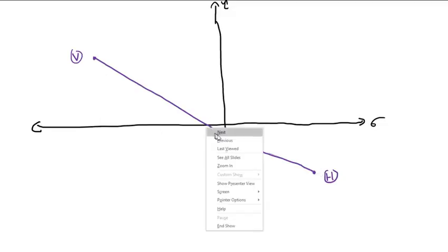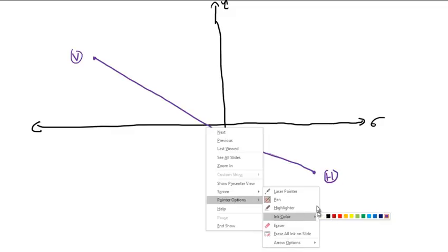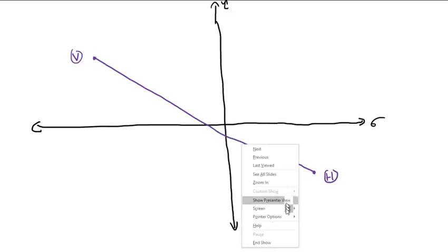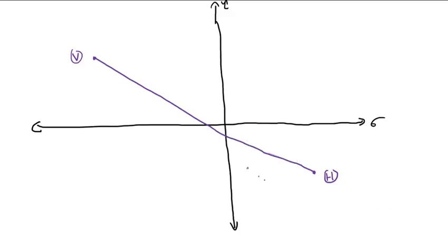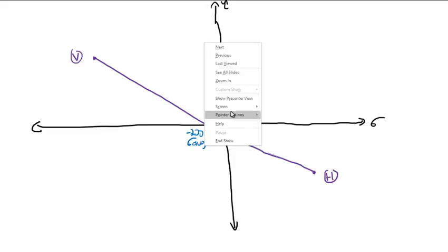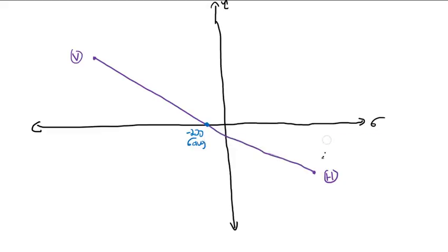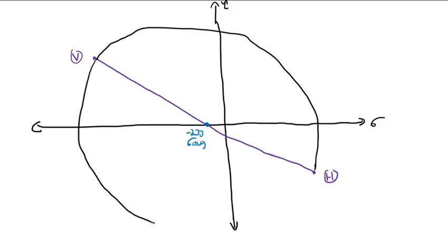And then we recognize the center of the circle is where the line between them intersects the sigma axis, the x-axis. So sigma average is negative 200. Then we form a circle around this. We just trace a circle around here. Now this would best be done with a protractor, but oh well. Another perfect circle, as I always draw them.